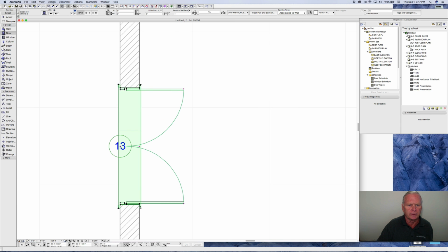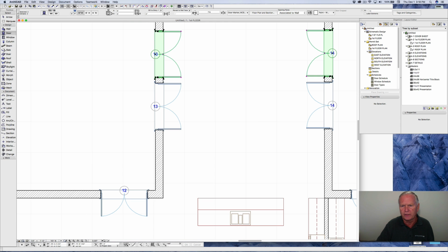And we're going to zoom in a little bit. And what we're going to do is we're going to right click on that hot spot right there, which is the opening in the wall. Right click on that, move, drag a copy. Okay, so I'm going to take that point with the little check mark and I'm going to drag it up, and I'm going to see that if I come up here, it's 6 foot 1.5, and if I want 8 inches more, that's going to make it 6 9.5. So I'm going to type D 6-9.5, and I'm in place. And I've moved both of those and I've put copies there.